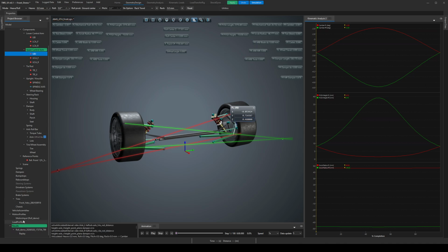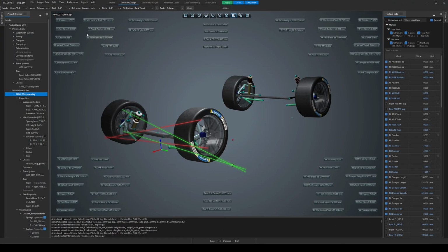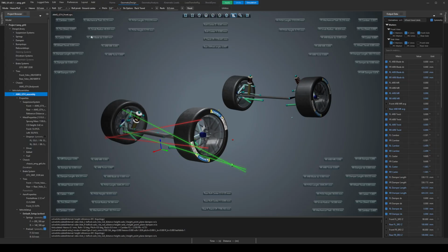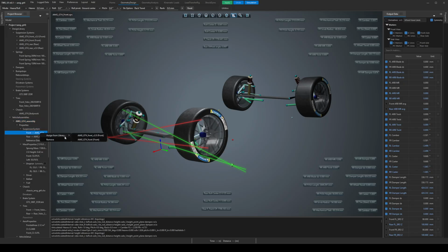One drawback of WinGeo was that, although it was theoretically possible to work with front and rear axles at the same time, in other words, at vehicle assembly level, the implementation was not especially convenient. At the top of the project tree there is a design library. This is where the user adds components that may be needed in the project, suspension files, springs, dampers, and so on. Below the design library there is a vehicle assembly entry. Here the user assigns the components from the design library that should be used in a specific vehicle assembly.